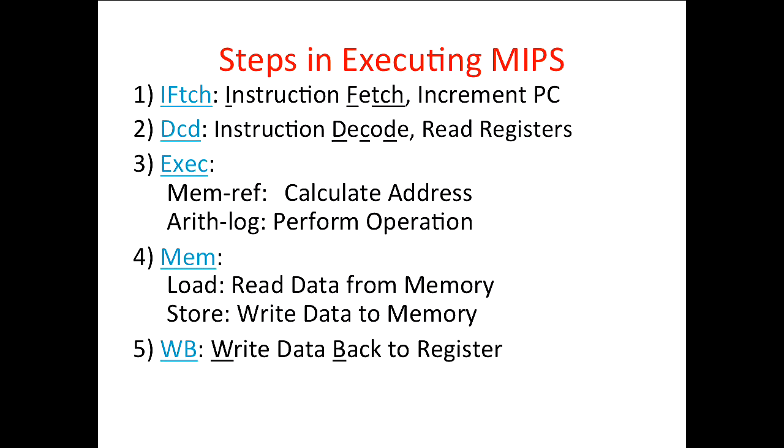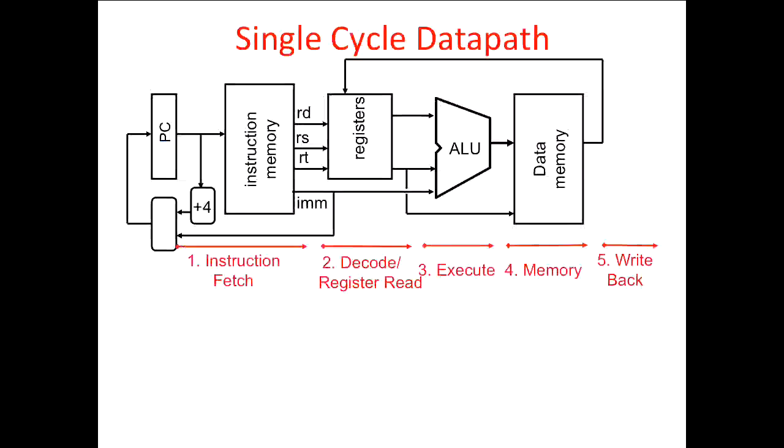Let's stop now and apply that to executing instructions. So in MIPS, we already called out these 5 stages of executing the instruction. You have instruction fetch, instruction decode, instruction execute, memory access, and write back. Now remember, not every instruction uses all of these stages. In fact, only the load instructions actually do all of these. But what we did is we set out that every instruction would pass through all those stages nonetheless. So what we're going to do now is take our single cycle data path and pipeline it.